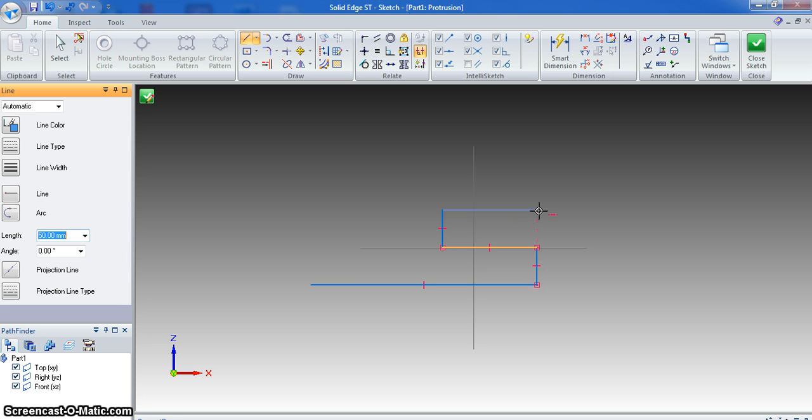You can see here we've got a vertical line coming off the bottom, sort of a dashed line, to say that point is going to be in line with the bottom line end. So I can just snap that, being for a horizontal as well, and then we're going to go up 32, so enter, and you'll see that the height's coming up. Again, it's going to snap to a vertical and it comes up with that little icon next to my cursor.